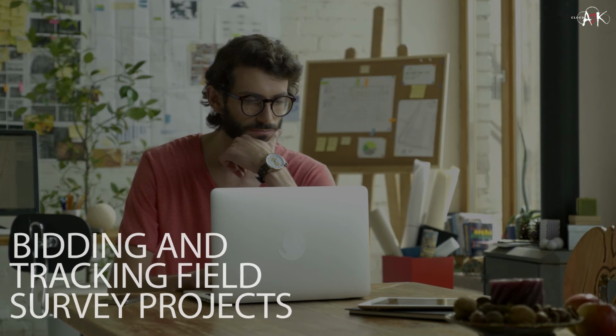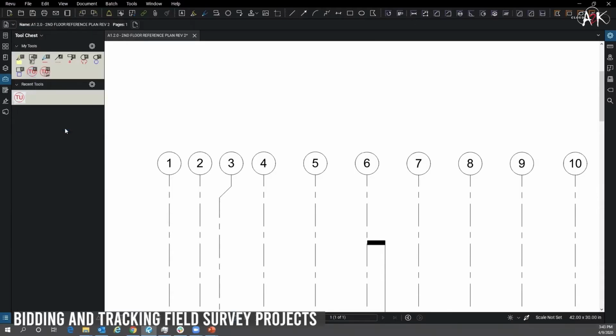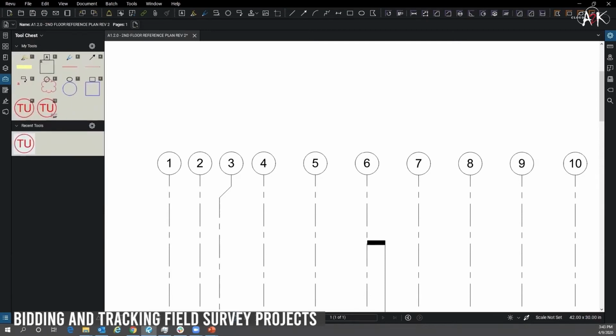Bidding and tracking field survey projects. Maybe you have a last-minute bid due for a scanning or survey project and don't have access to the site. Using the sequence or count tools in Revu, you can quickly mark all the locations you'll need to perform a scan. Each mark represents a setup, scan, takedown, and processing, allowing you to estimate the time needed.